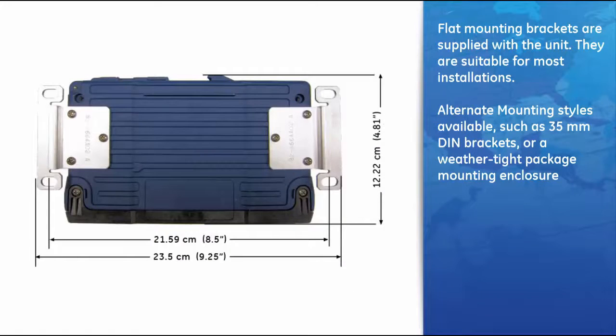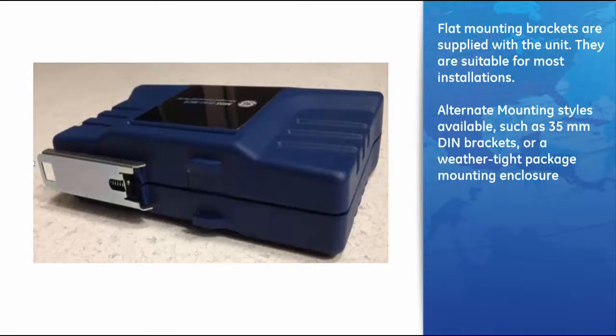The Orbit is supplied standard with 2 flat aluminum mounting brackets, and these are suitable for use in most installations. The brackets are attached at the bottom of the chassis with 3 screws each as shown. These brackets allow mounting the Orbit to almost any flat, stable surface. Other mounting techniques are possible, including a 35mm DIN bracket and a weather-tight packaged enclosure for pole or wall mounting.